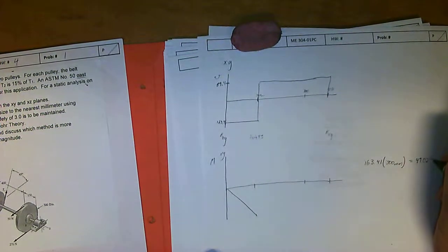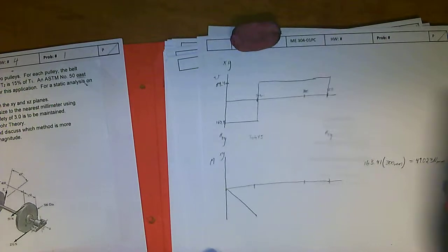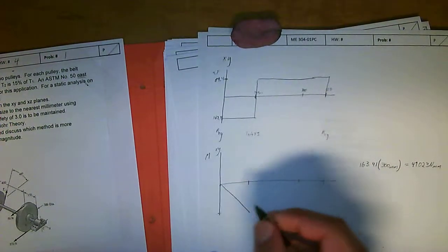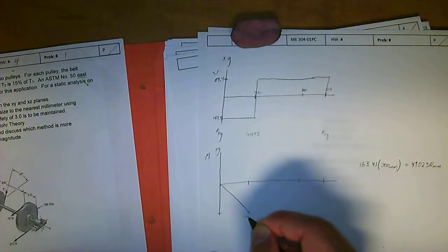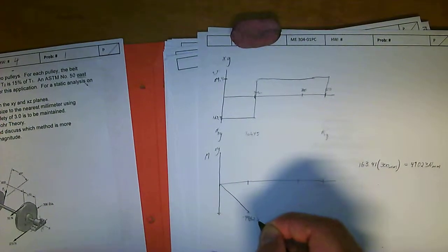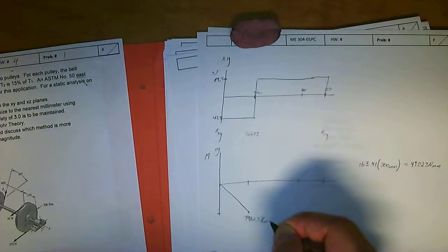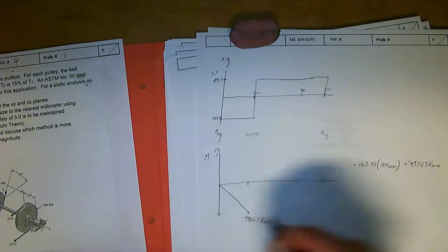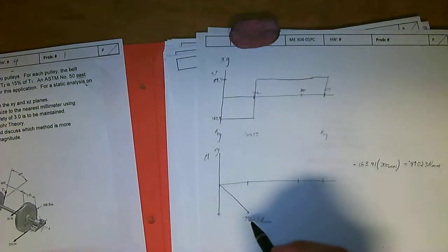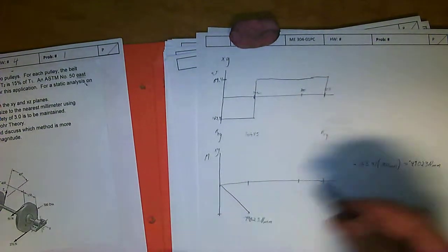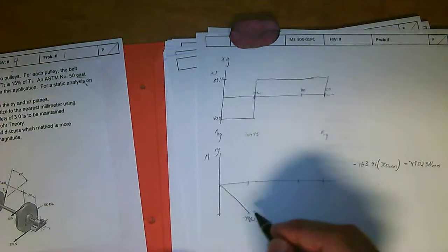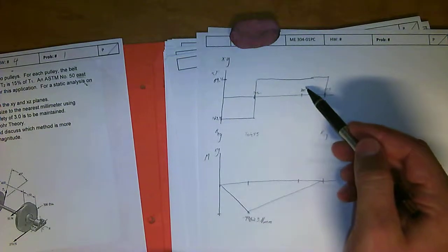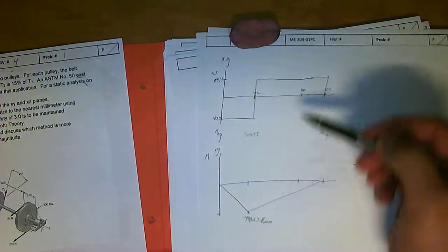Cool. Alright, so we have this down here at negative 49,023 Newton millimeters. And actually, this is negative 163, so negative right there. So you know it's a negative slope, and you end up with a negative moment, so great. And then again, since you know it has to go to 0, you can just draw a straight line across from here. And you also know that this is all a positive value, so it's going to be a positive slope down here. And we're good, and you can make that assumption. And if you want to check, fine, but we already did the sum of the force equation.